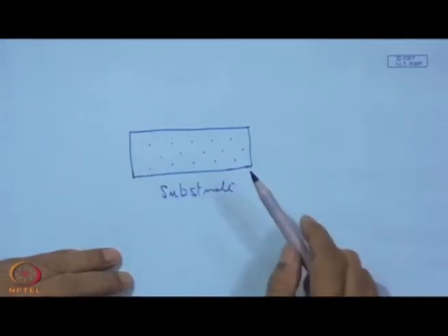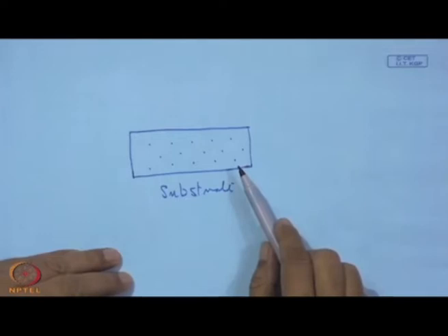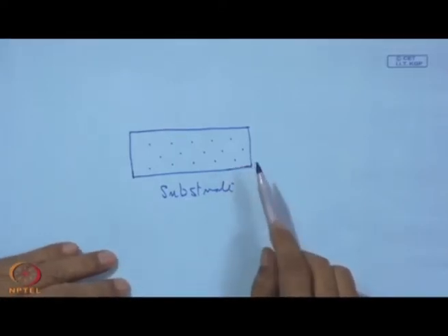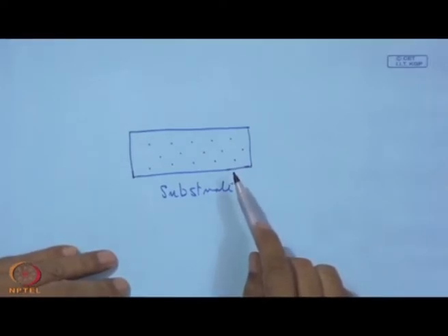So, these are the areas where diamond growth or nucleation takes place, that means first of all adsorption of the reactive species, then dwelling or residing on that place, and then reaction, that is the third step, and then we have nucleation of diamond, which is going to nucleate and then grow in volume.